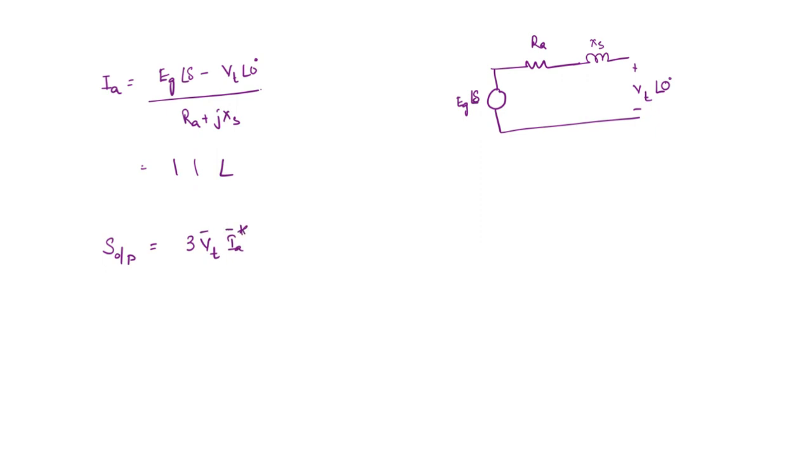We're talking about the phasors here. Okay. So we know Vt, magnitude Vt and angle 0, and Ia we find out the magnitude and phase from this expression. Then you write the conjugate of it. Okay. So now whatever real and imaginary part that you're going to get, from there you're going to get the real power and imaginary or the reactive power. Okay. So P output and Q output. This is the procedure if you are not neglecting the armature resistance.